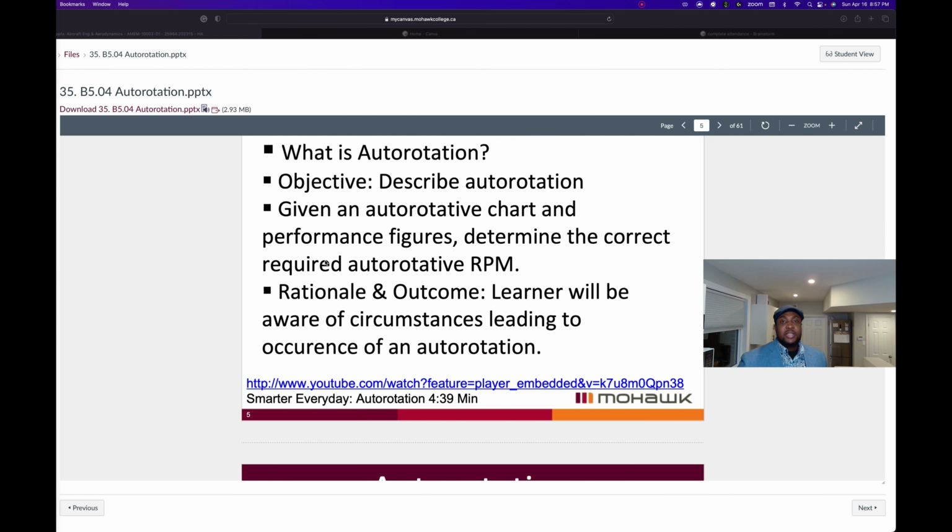The next step for the pilot would be to lower the collective lever. The effect of lowering the collective lever helps us to maintain main rotor RPM and allows the pilot more time to aviate and to think about a possible strategy for landing the helicopter.